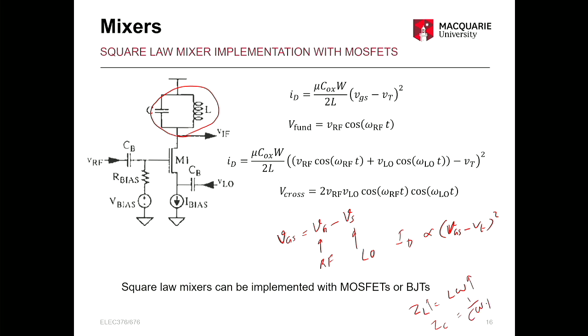As omega goes up, the impedance of the capacitor goes down. So there is only a specific region of frequencies at which this will pass the frequency. That's called a band pass filter, or you can also make a band stop filter using this.